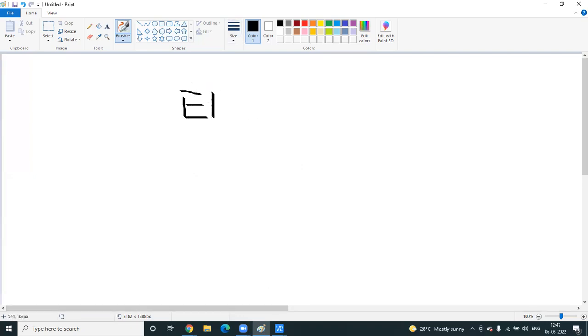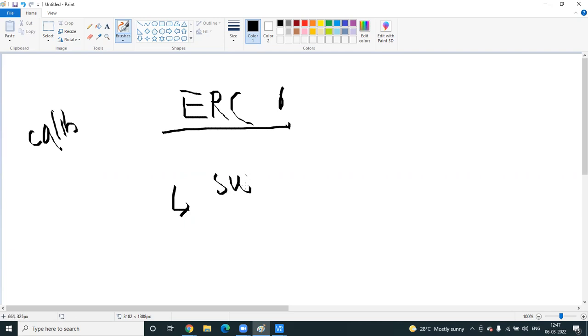Next, ERC, electrical rule check. Actually, in the Virtuoso, we don't have this. You will find it in Calibre. So, ERC is the part of LVS when your body is floating. Not only body. Suppose P mass is not connected, so supply is floating. That time ERC will find supply floating, means your VDD and VSS or ground are floating, not connected. That time you will find this error. That's called ERC error, electrical rule check error.